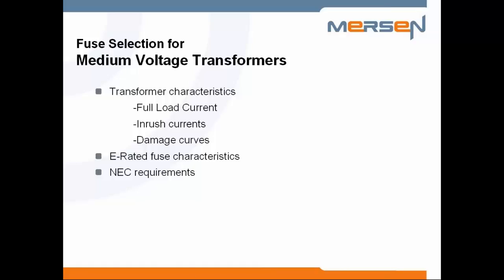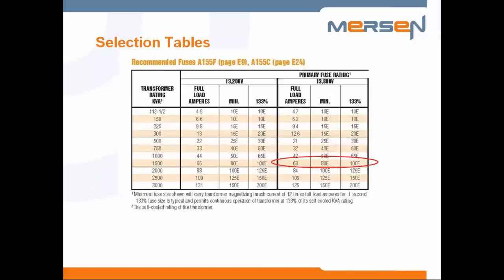And to a lesser degree of a limitation is the code requirements. With the electric code, you're allowed to size to fairly large size on these, 250%, which is not a limiting factor. Another thing that may limit your selection would be other protected devices upstream or downstream, and those vary quite a bit from application to application, and that's why you can use EasyPower to solve that. But the basic limitation for fuses for this arc flash phenomena is the limitations on the inrush and full current.